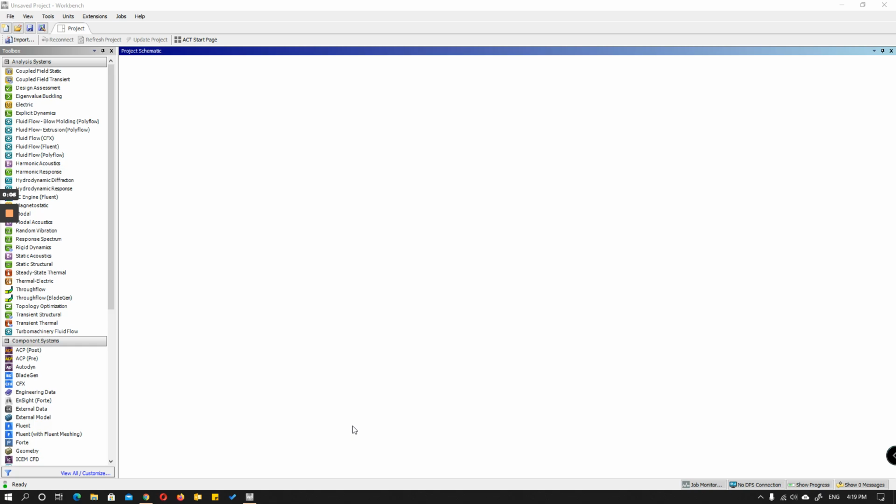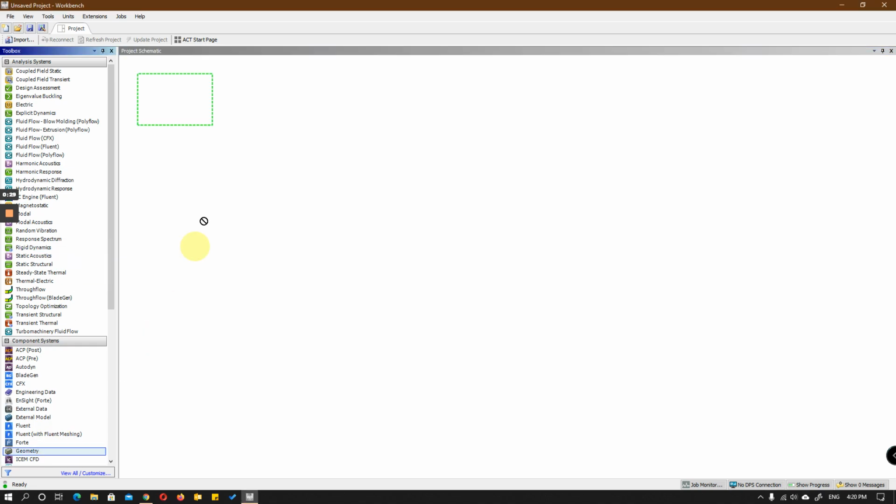So what we're going to do today is structured analysis on a tapered wing. Okay, so we are going to try to learn some structural data about a loaded aircraft wing. So we'll just take a normal aerofoil and we'll just try to analyze it over some particular length of a wing. Okay, so for the first we will require an ANSYS Workbench and we'll require geometry.